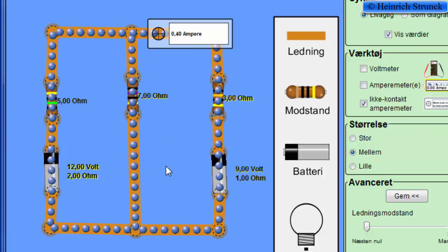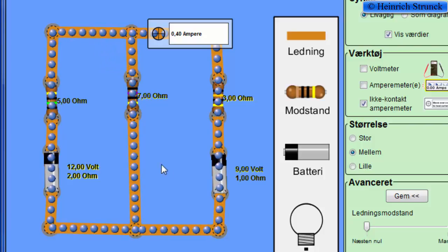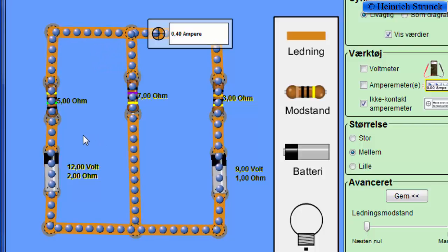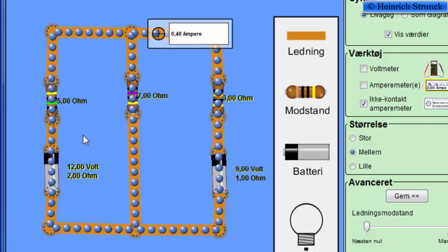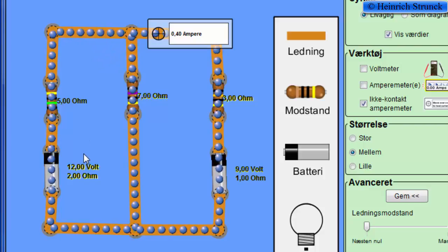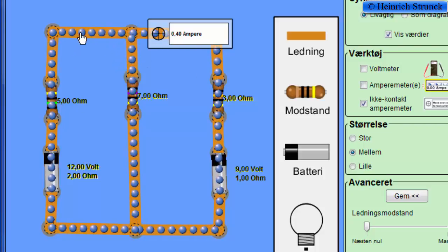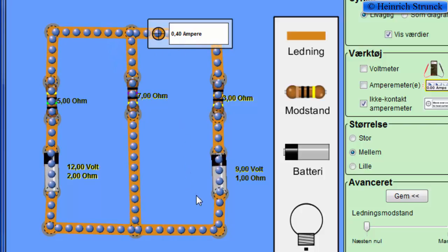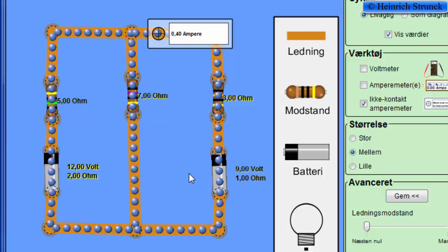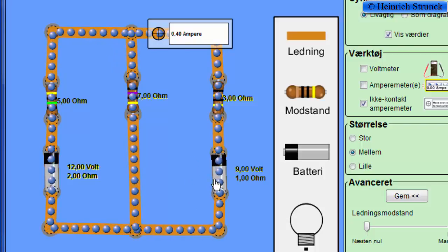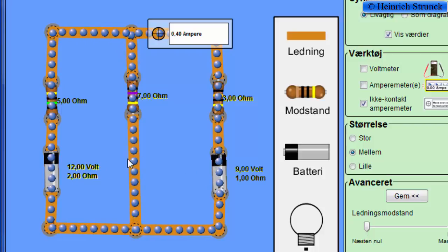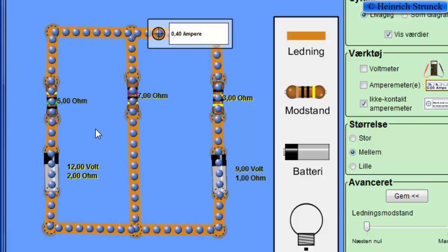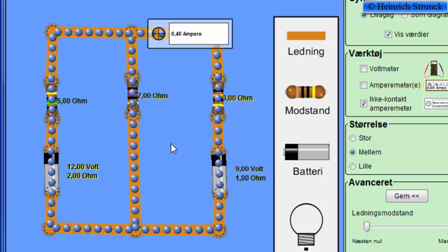If you think that Kirchhoff's law is very difficult, I'll give you an alternative. It is the superposition law. With the superposition law, we also calculate the currents I1, I2 and I3. We just calculate it in 2 steps and then add the currents at the end. It is only 2 times because we only have 2 supply systems. If we had, for example, 4 supply systems, we would have to calculate all the currents 4 times.